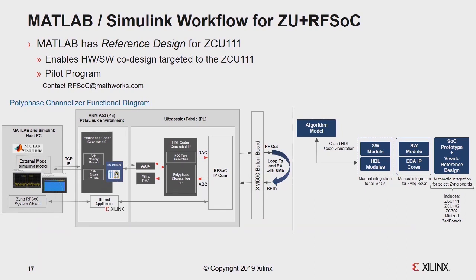The other tool I want to give a plug to, you can go out and see at MATLAB. They have a demo of this. It's not widely promoted, but it's basically a tool that MATLAB did, and it works with the ZCU111, so it's targeted to that. You can build a model in MATLAB, and the best part is that it will target some of the code for the programmable ARM processors and also target the code for the programmable logic, hooks up all the AXI buses, and you can do a demo quite quickly with this particular tool.